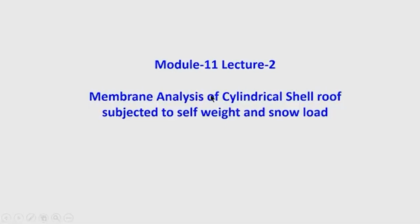vertical loading, that is self weight along the surface of the shell and also the snow load along the projected area. So, today our discussion will be on the derivation of the expression of the membrane stresses for cylindrical shell roof subjected to self weight and snow load, and we will be incorporating the different types of directrices in the expression. So, a general expression is targeted to find out the membrane stresses in the cylindrical shell roof,